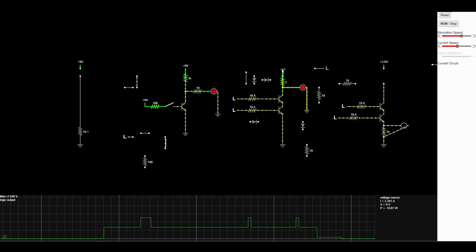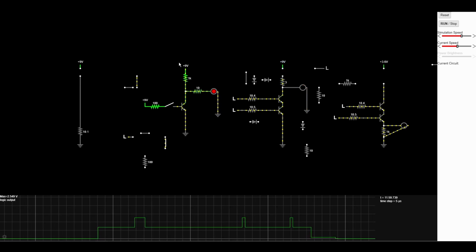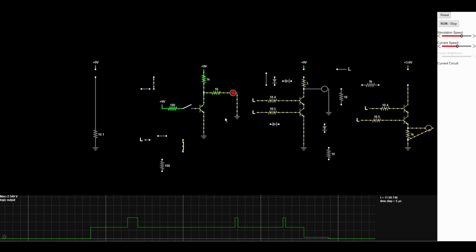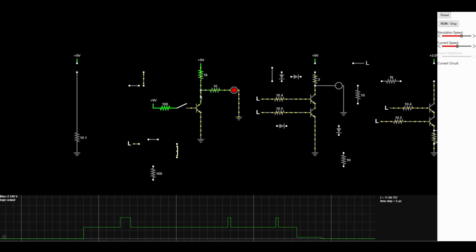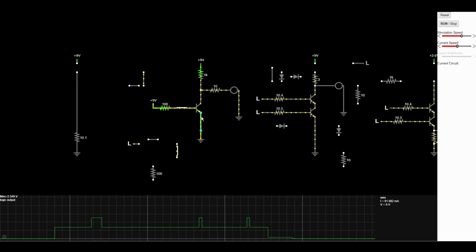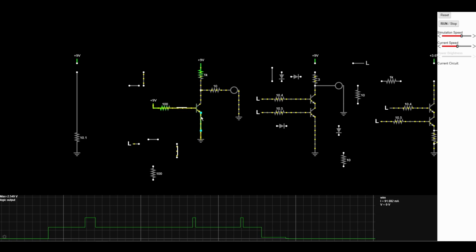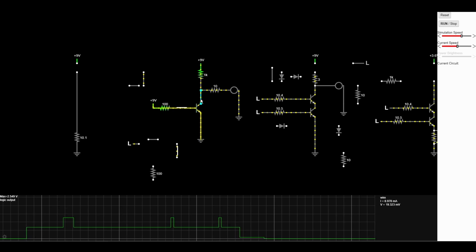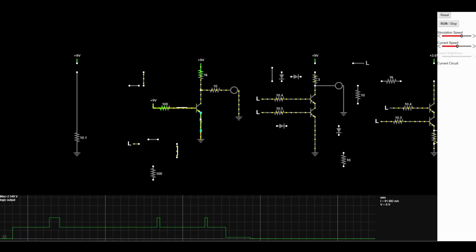Similar over here. Go ahead. Unplug these guys. So this one over here, you can see from this, it's showing that the current through this wire should be about 7 milliamps. If this is connected, current through here is 91 milliamps. Oh, actually that is quite a gain, isn't it? There's a gain in current from here to here. This is 8 milliamps, and down here it's 91 milliamps. So there is a significant gain between these two.